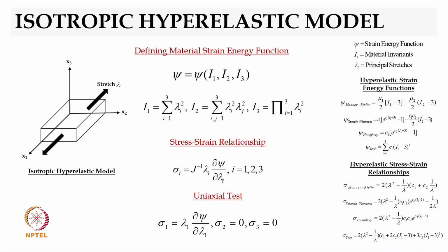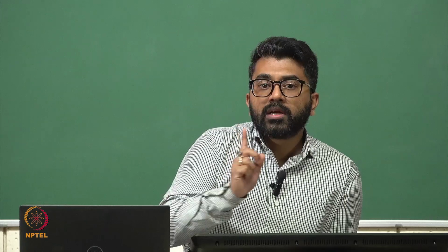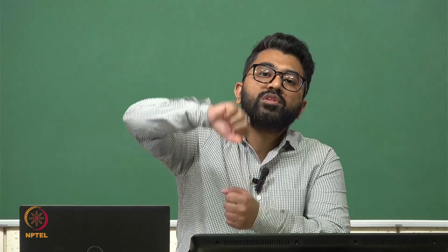This is achieved not only through the partial differential equations, but also by applying a uniaxial test condition. The majority of the hyperelastic material models have been focused on isotropic, which is a simplified version. Most of the tissues are not isotropic, by the way. They're focused on isotropic, as well as on the uniaxial test, which is when you just pull the tissue along one direction. They are not focused on biaxial or multiaxial tests, which are typically the boundary conditions which a soft tissue would face.